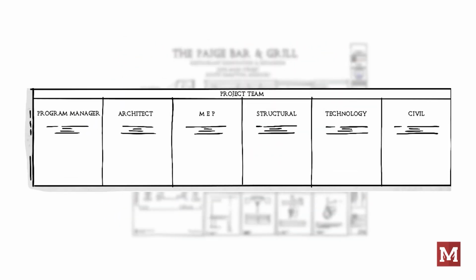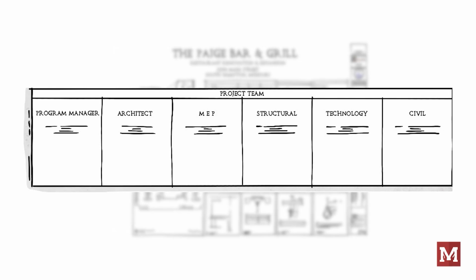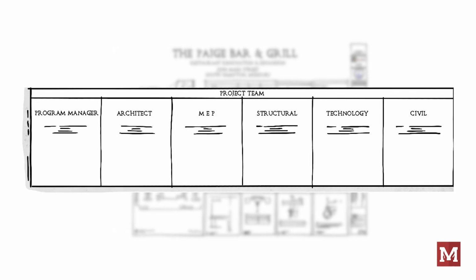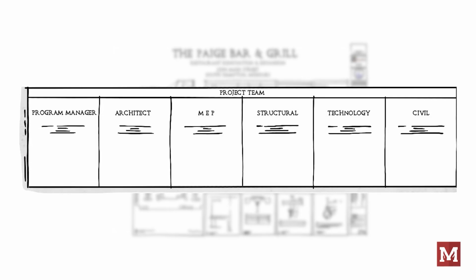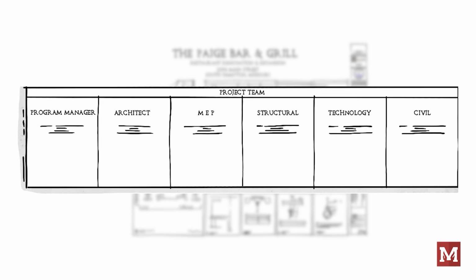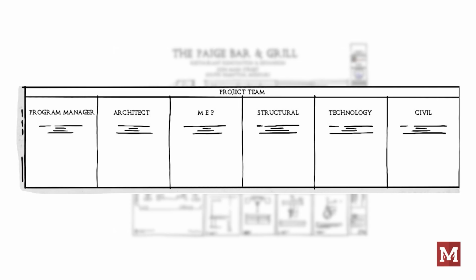There will generally be a project directory, which amounts to a sort of who's who related to the project. This usually lists the owner, the tenant if different from the owner, the architect, the structural engineer, the MEP engineer, and the authority having jurisdiction. In my state of Texas, we usually don't list the entity responsible for fire protection design on this sheet, but every state is different. The reason we don't list this in Texas is because fire protection system design requires a very specific license through the state fire marshal's office, and our design work is a deferred submittal after the building plans have been completed and submitted.